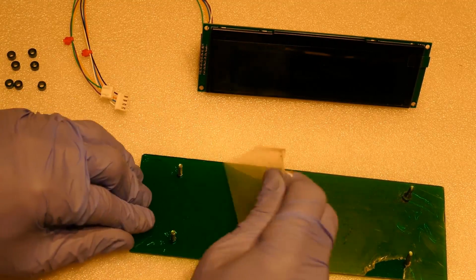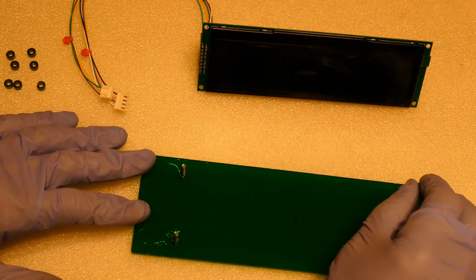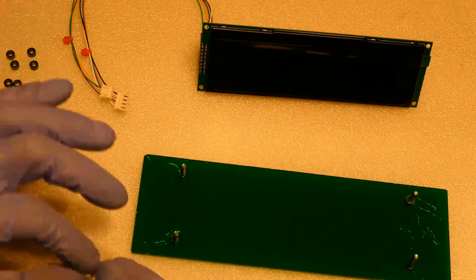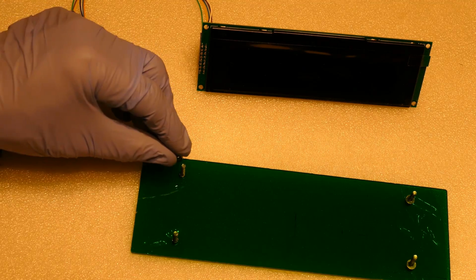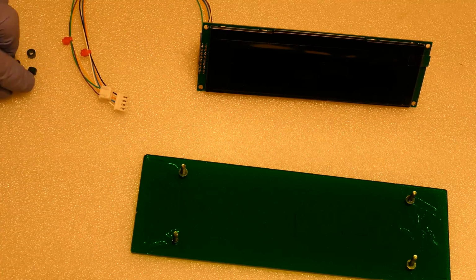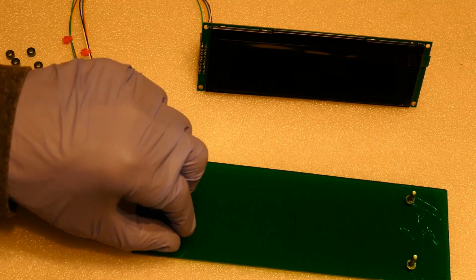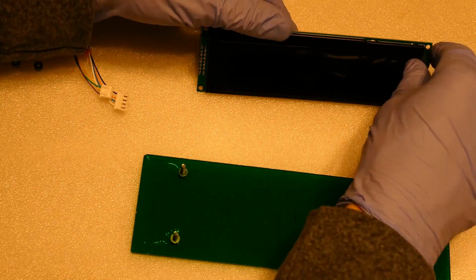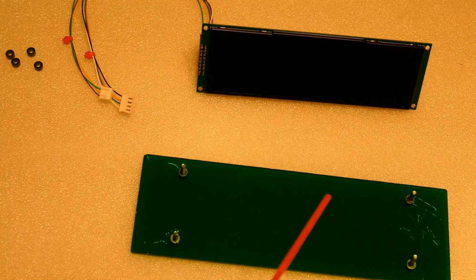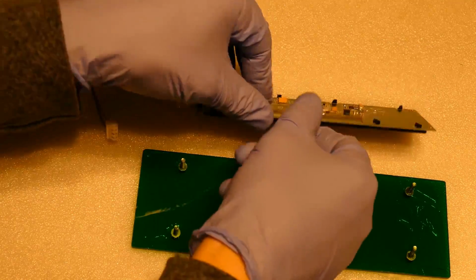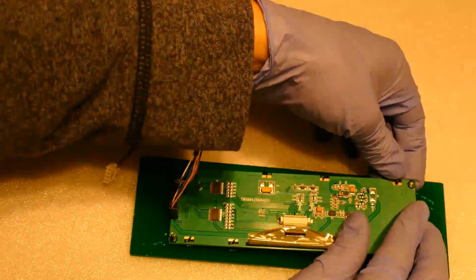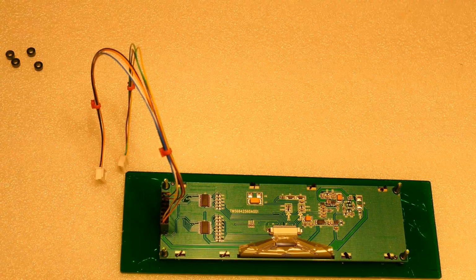The plastic is fully removed from the other side. M3 by 3mm green anodized spacers are inserted to hold the cover above the display. I had to file down 2 of the spacers because the holes on the OLED were a little too close to the frame. The plastic is removed from the OLED. The display is sprayed with compressed air to remove any dust before the cover is put on. The CNC cut holes line up perfectly with the OLED holes.